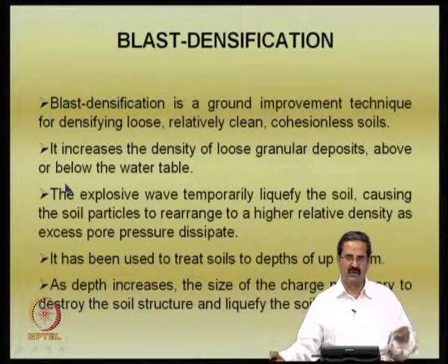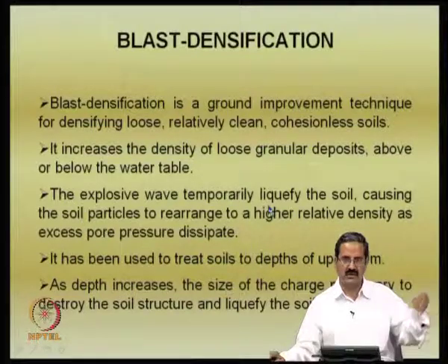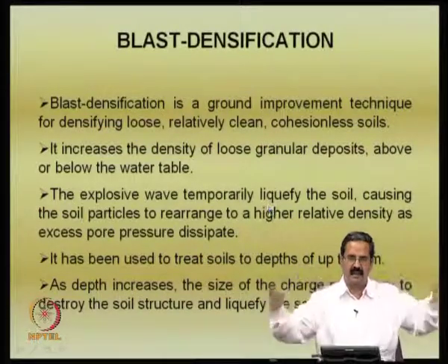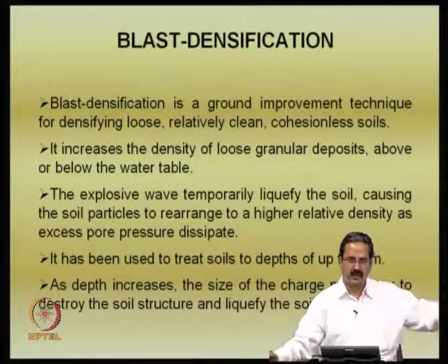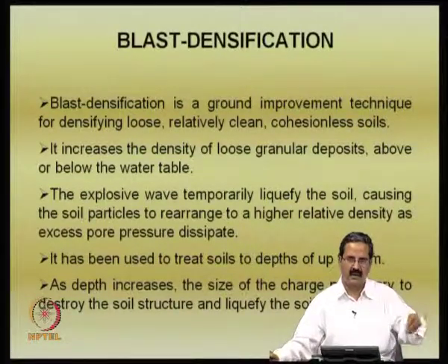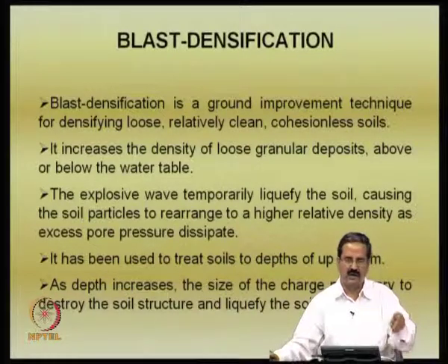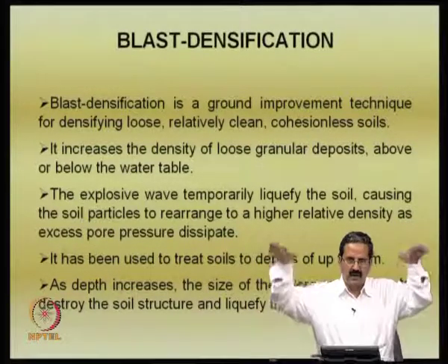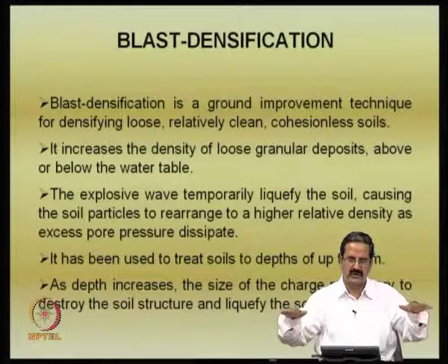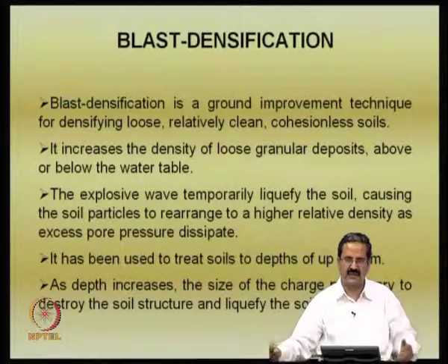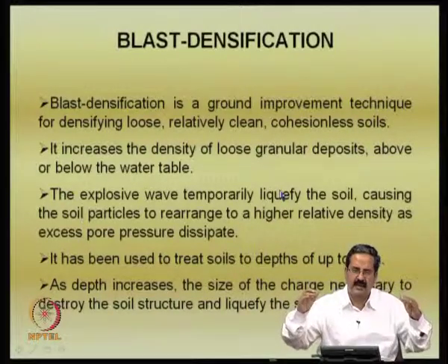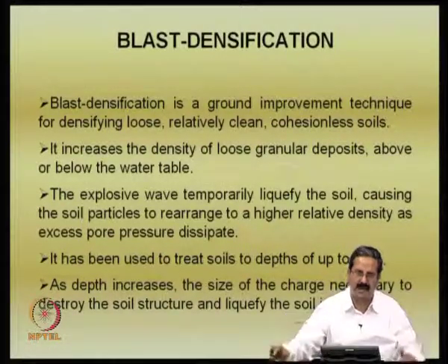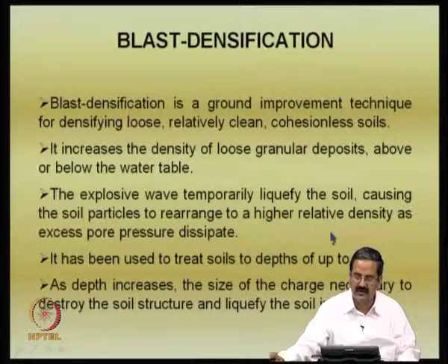And what we do is that we try to create some explosives. You introduce blasts, like there is some 10 meters of area which is there, a sand deposit. You put a blast somewhere some 10 meters down, then trigger it, then the whole area settles. So, the consolidation is there in that sandy area. You are trying to densify the whole area, that is the actual system here. You are essentially trying to densify.